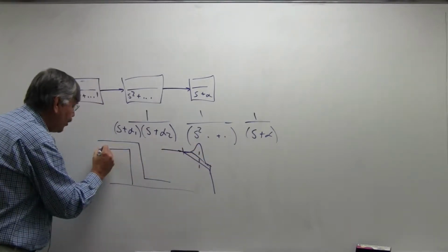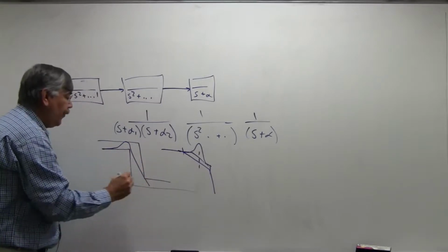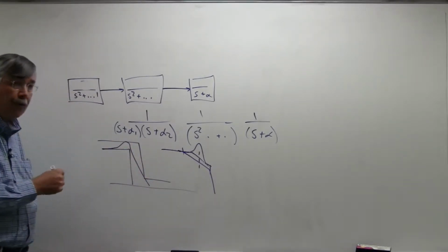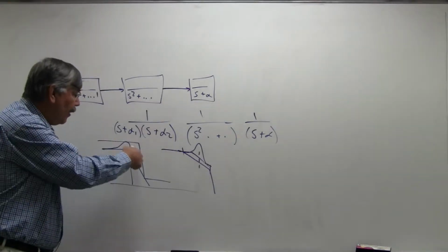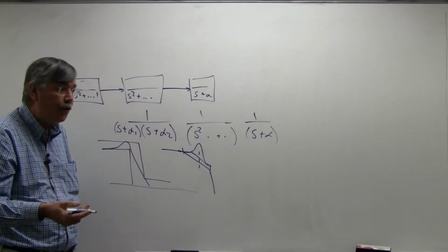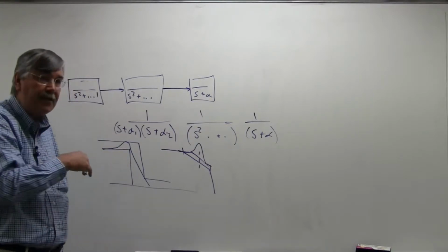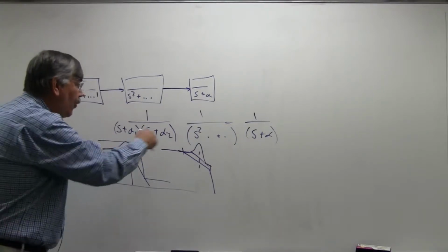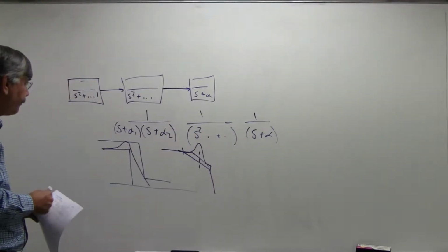And maybe that's just what we need, because the peaking would then allow us to fit this thing maximally as it goes through this thing. So typically, to increase selectivity, some of the poles are going to have somewhat higher Q, and most of the time, for most interesting filters, the poles will be complex conjugate. So that's why I sort of assumed that these were complex conjugate pole pairs.